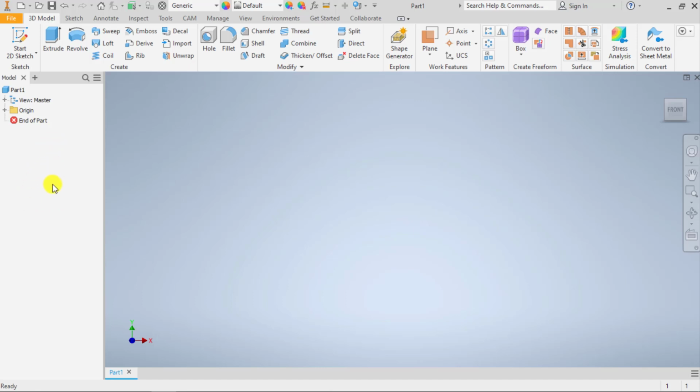This is very important. This is a chronological ordering of your part and how you made it. So for those of you that are familiar with AutoCAD, while they're both made by Autodesk, the same company, there are a lot of differences. In AutoCAD, I couldn't tell how you made a drawing, if you mirrored something or if you just redrew the other side of, let's say, a symmetric part. In Inventor, I can see exactly how you made every single feature in a part.